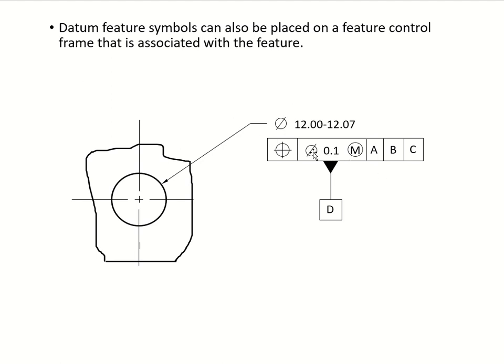It's just telling you that this datum feature D is associated with this diameter of this hole right here in this part. And tolerance is going to be right there. When you pay attention, your brain is going to start thinking and get confused. That's your lower limit, and that's your upper limit. You don't have the value dimension. So that's another way of writing tolerance. So you know that you're giving a tolerance range. Here it's just giving you the tolerance plus or minus 0.1.